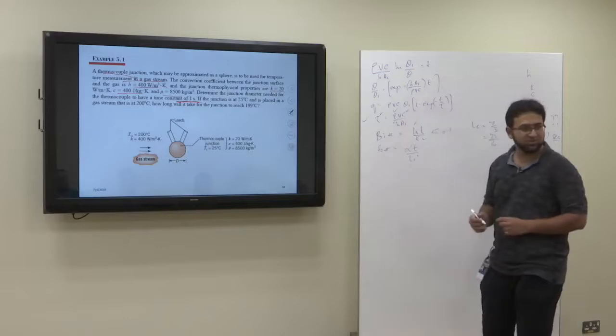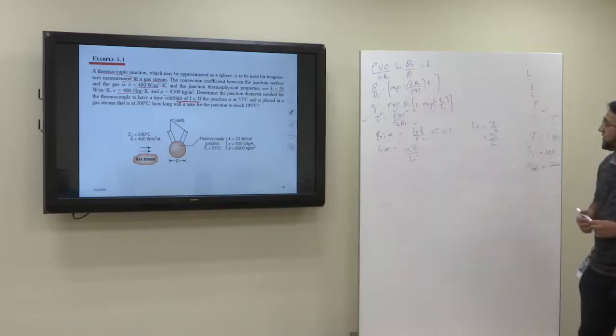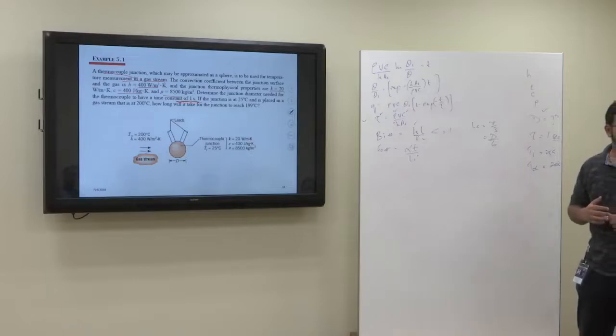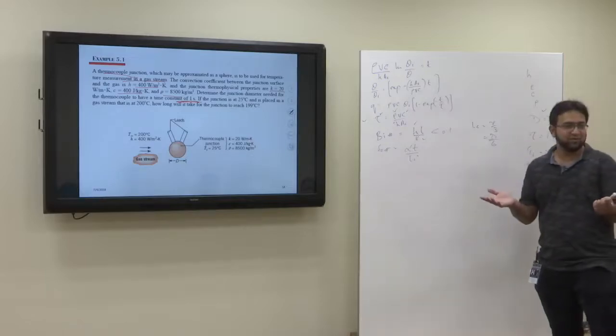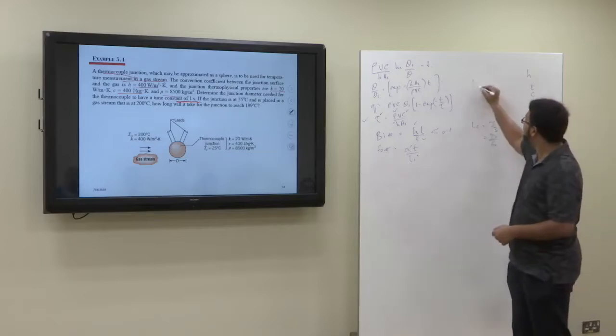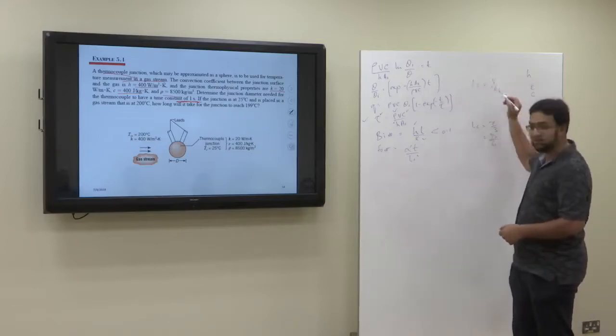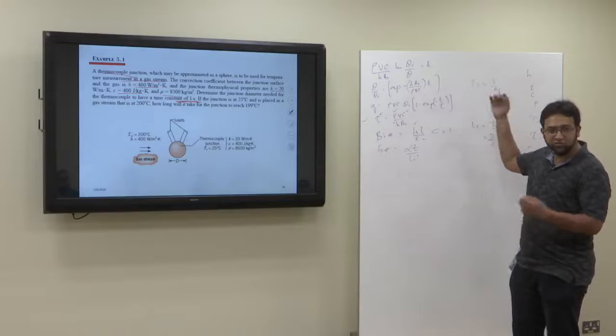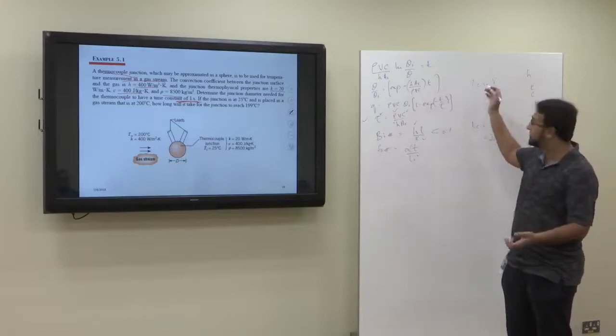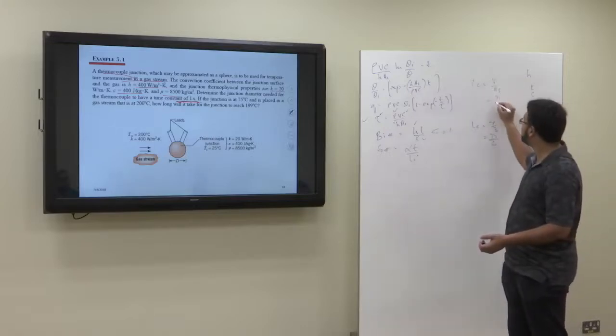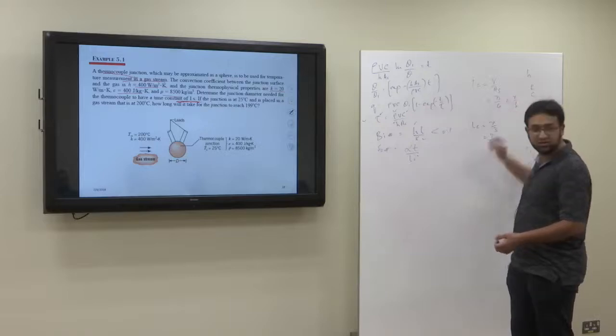These are the three properties that we have. We don't know volume, and we don't know the surface area. But that is the formula for the characteristic length. Characteristic length is equal to volume over surface area, right? And for the sphere, when we place the values of the volume and the surface area, it comes out to be diameter upon 6 or r upon 3, right?